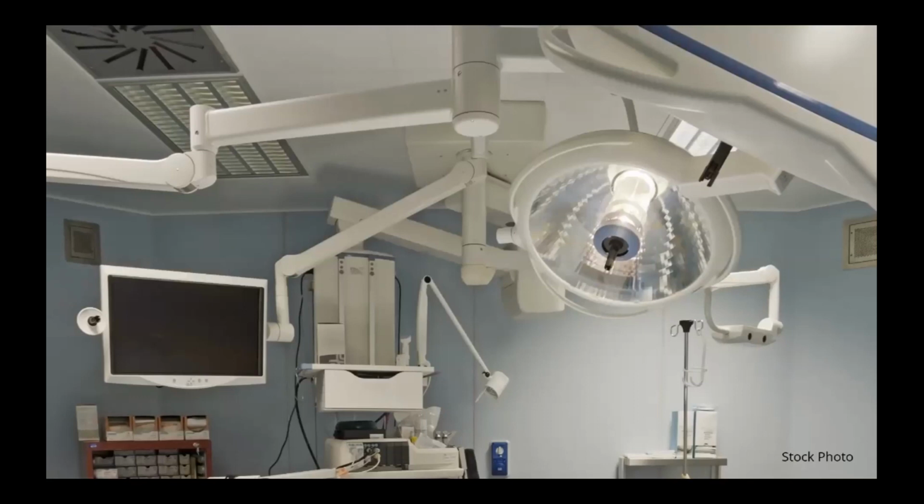So in this image, we see what's obvious, an OR space because of the equipment. And one of the things that jumps out at you is if you look up in the ceiling, you have this swirl diffuser located right next to a light fixture. So we don't see any laminar flow diffusers anywhere. So the fact that they're using a high mixing swirl diffuser, I would not consider this space to be ASHRAE 170 compliant.